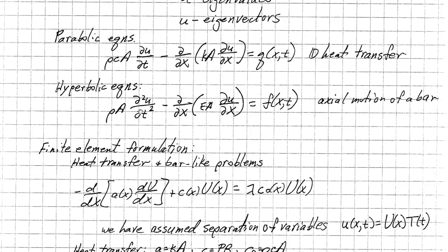Second one is for mechanics, this is a force balance. You have your stress-strain behavior, or really this is divergence of a stress. You may have a distributed load, and this basically is distributed force. This is an internal force due to changes in stress, and that has to balance with acceleration times mass. So this is a density, a cross-section area, and your acceleration.